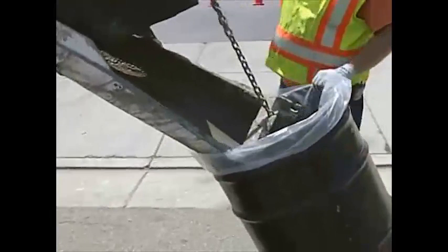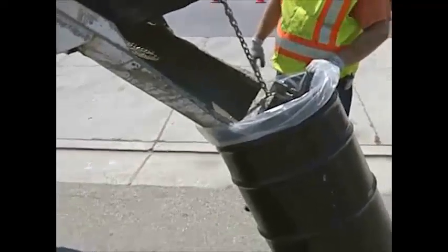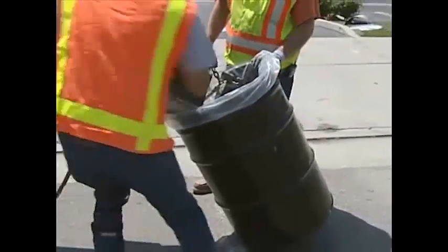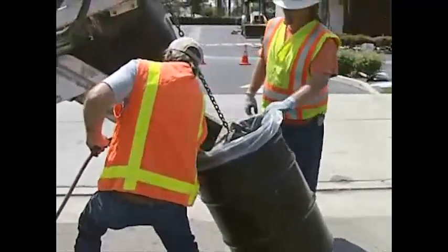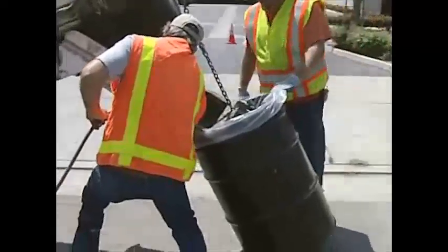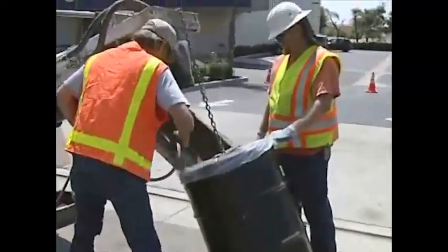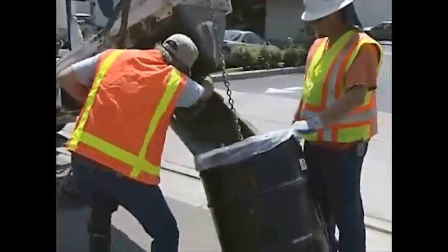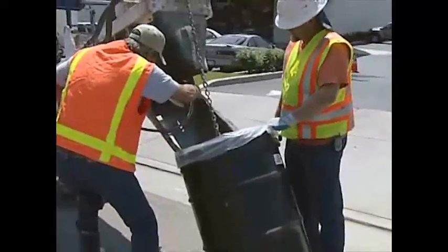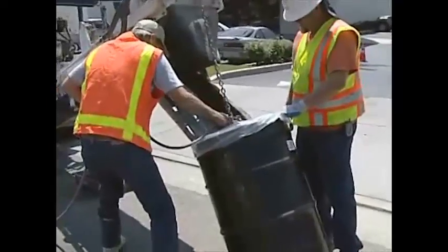Collect washout in an impermeable bag or container for disposal, and be sure to pump the excess concrete from the concrete pump bin back into the concrete mixer truck. Concrete washout from concrete pumper bins can be washed into concrete pumper trucks and discharged into a designated washout area, or be properly disposed of off-site.